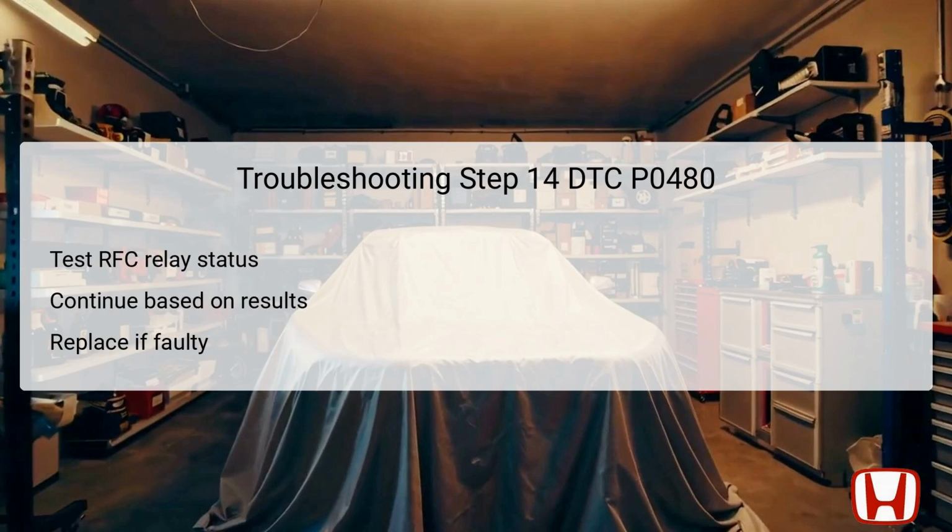In the 14th step, conduct a final test on the RFC relay following any previous electrical checks or repairs. This ensures the relay's operational status is confirmed prior to finalizing troubleshooting. If the relay is determined to be functional, the process can advance without further actions required pertaining to that component. If it exhibits any issues, immediate replacement of the RFC relay is necessary. Its performance is paramount, as it directly controls the operational state of the radiator fan, critical for engine cooling.